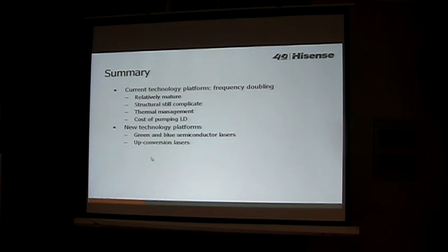For this erbium-doped amplifier, we know its working wavelength is 1.5 micron, but through upconversion, it will generate some green light. And also for the erbium amplifier, because it's used as a backbone in a communication system, usually you use it in, say, undersea cables. 10 years ago, it happened.